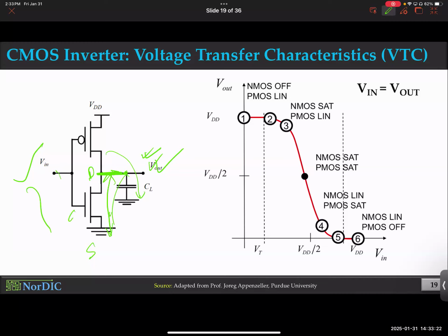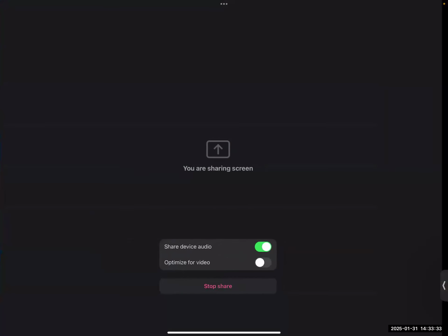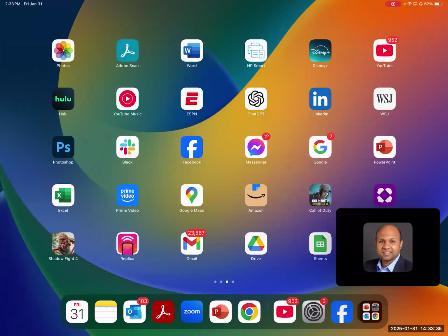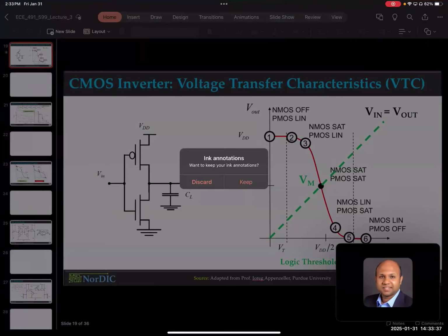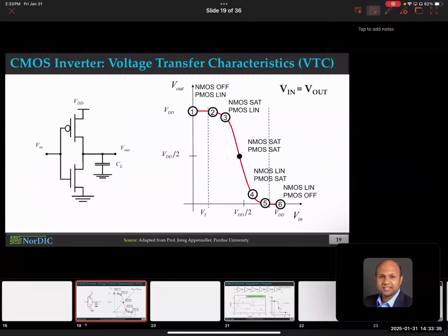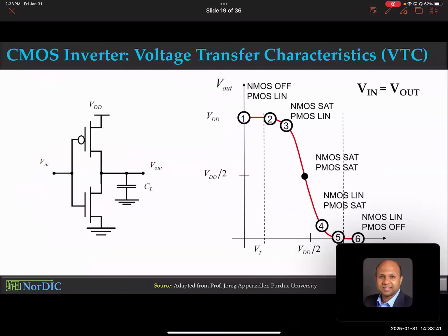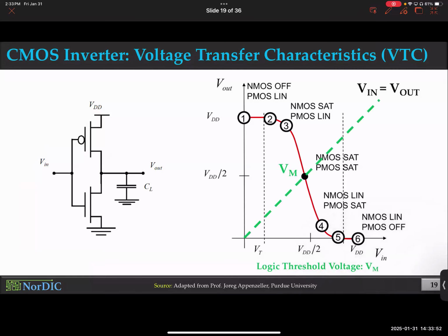And that input is the gate of this transistor and also the other transistor. So when you change the input, your gate to source voltage changes. At the same time, your output is changing, so your drain to source voltage also changes. Sorry, I think I clicked on that for some reason. Am I making sense? So you have two inputs simultaneously changing. Therefore, this is a complex situation. It's not a standalone transistor. Make sense? Okay. All right.